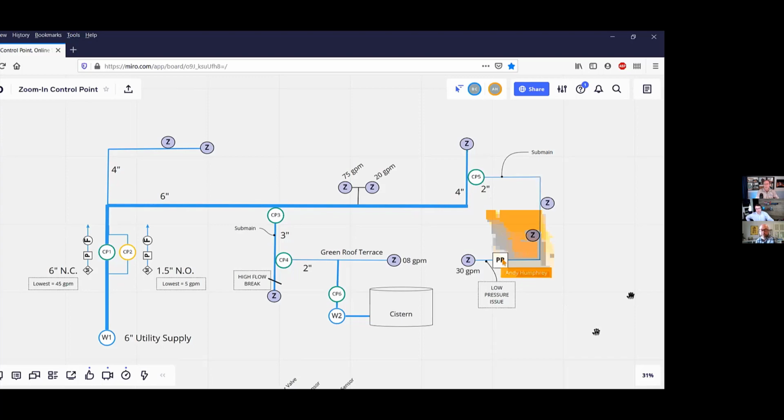Yeah. Maybe the pressure's only dropping at certain times of the day. And I think Chris mentioned this a couple weeks ago that a 10% drop in pressure can have a 40% effect on the water distribution. And this is the far extremity of the piping structure. Typically this is where pressure issues sometimes come to be, especially if the piping wasn't sized correctly and you're noticing that perhaps the distribution is not correct. You can go ahead and add a pressure transducer and start tracking the data there.